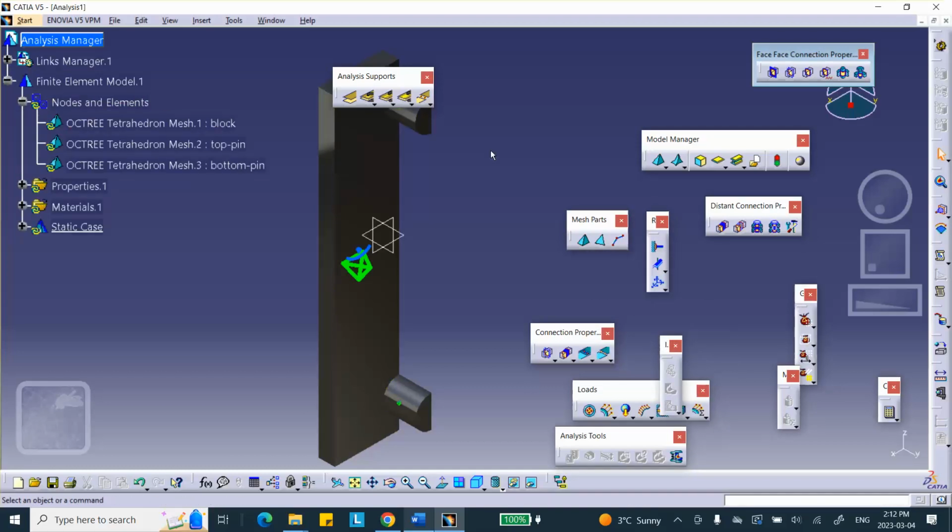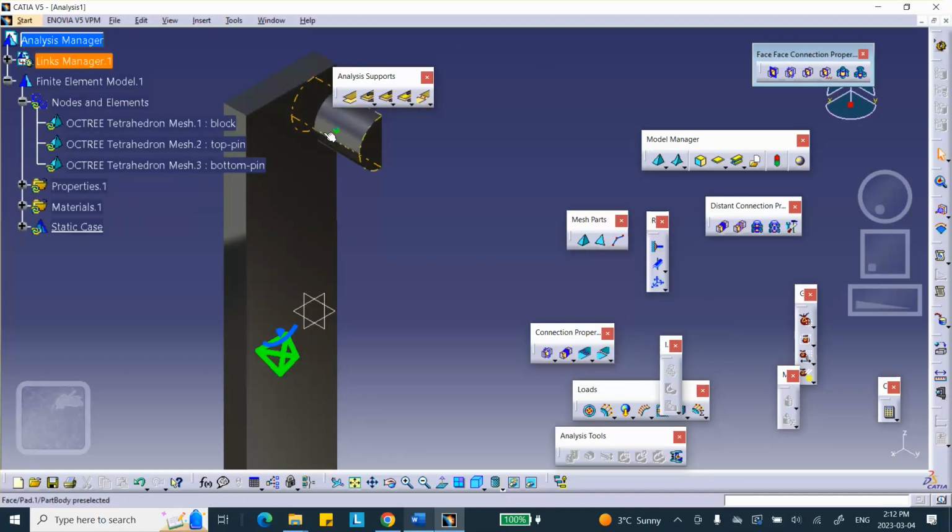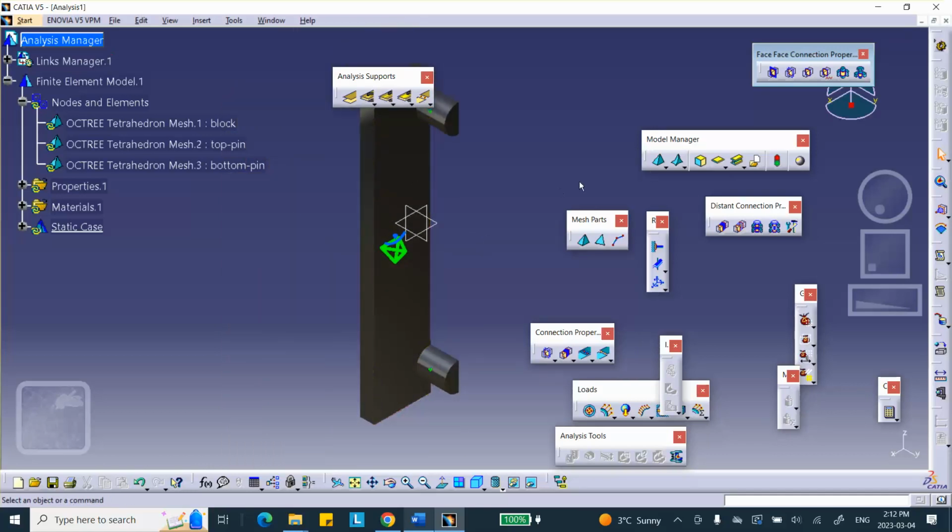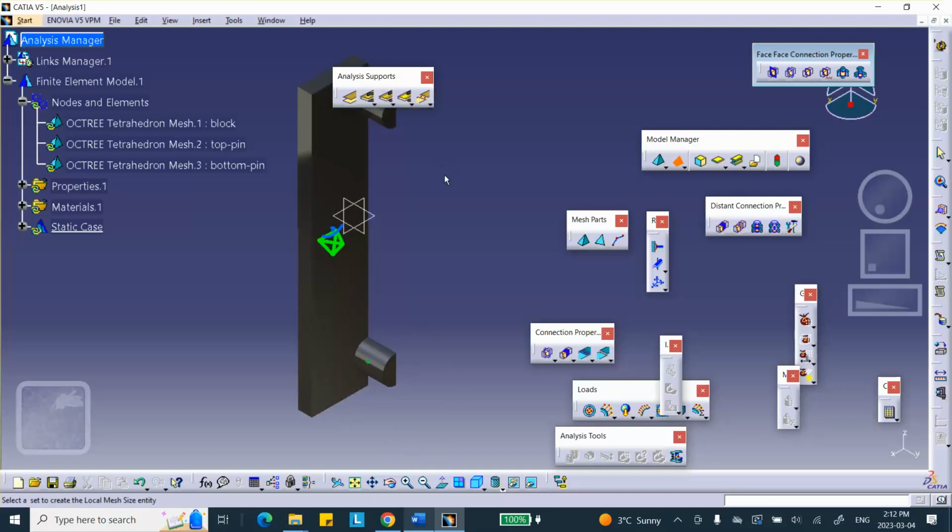However, I will do a mesh refinement around the hole here and the bottom hole. I showed you in class how it's done. You go to the model manager where the traffic light is, exactly like you did on the midterm. You click on it, it says, where do you want to do local mesh? Notice that nothing happens, because you have to read the bottom left corner of the window. It says select the mesh to be refined.